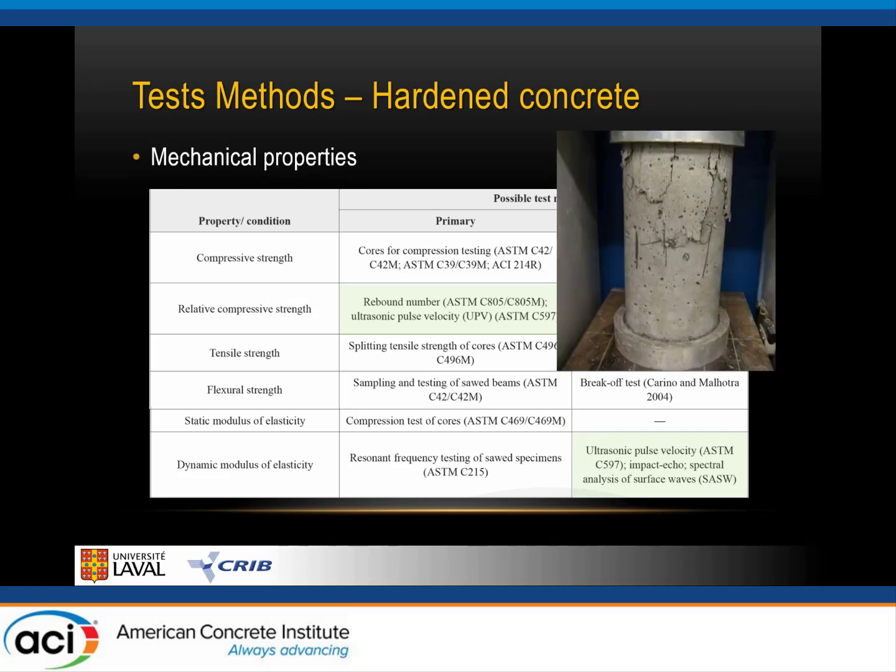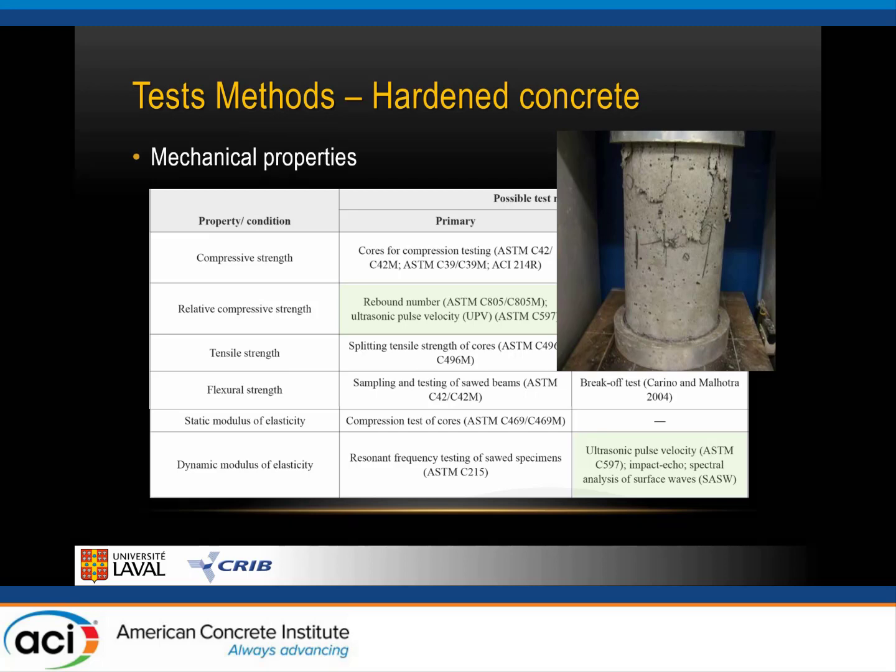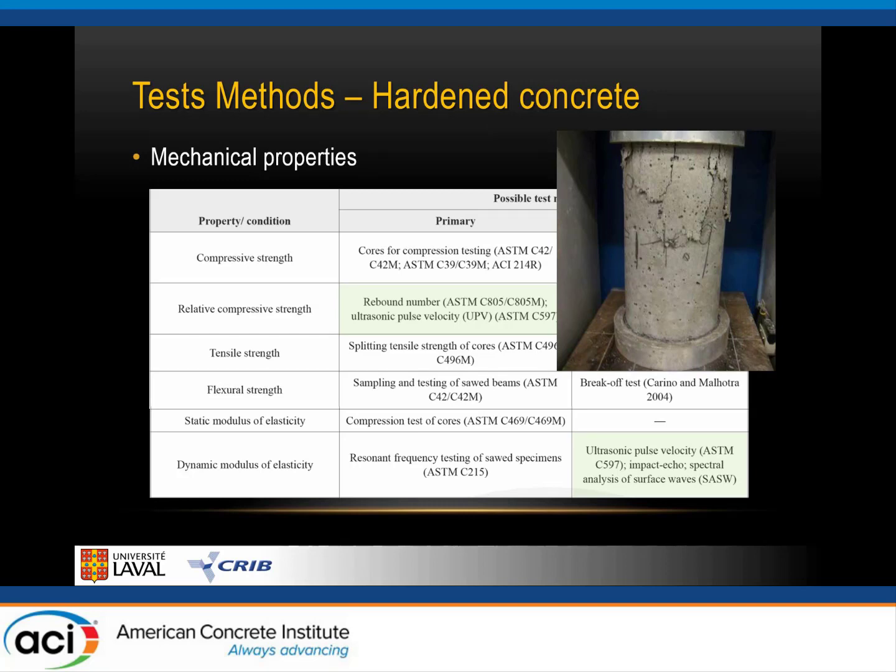So typically, the most common test that is being performed when taking cores to the lab, when assessing a concrete structure, for sure, is compressive strength. This provides information on the actual quality and uniformity of the concrete, and when needed and properly treated, it provides information to evaluate the actual on-site, in situ strength that can be used in performing a structural evaluation.